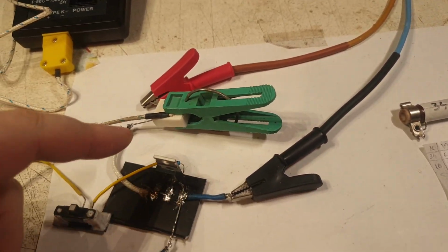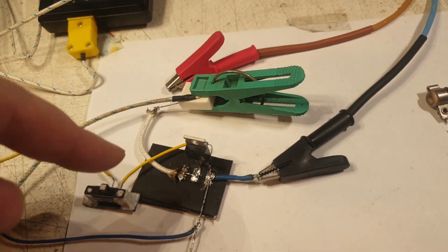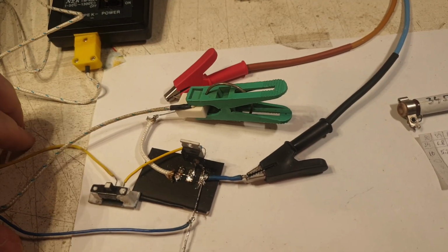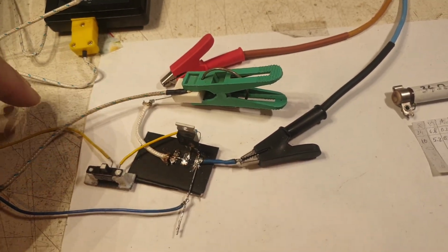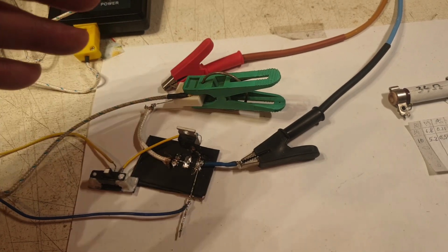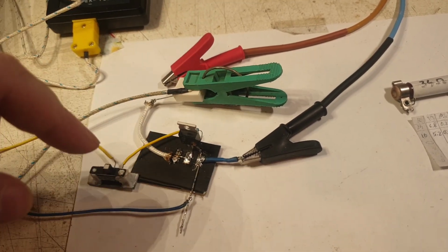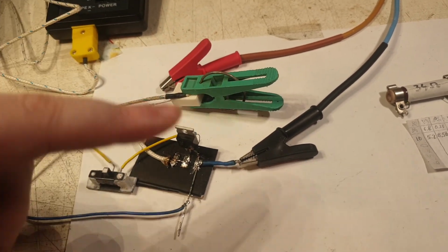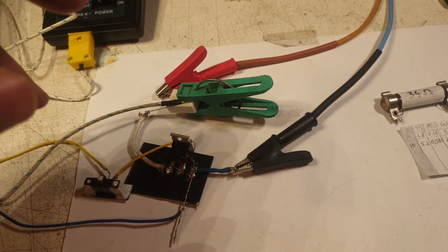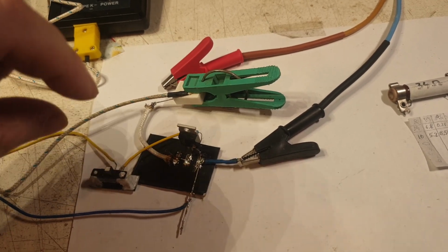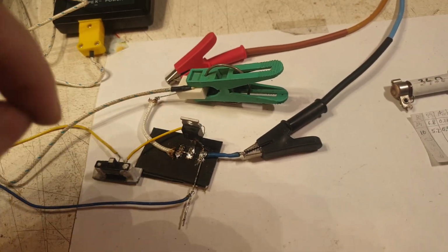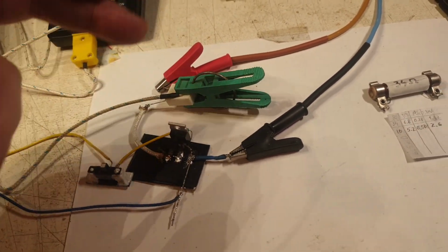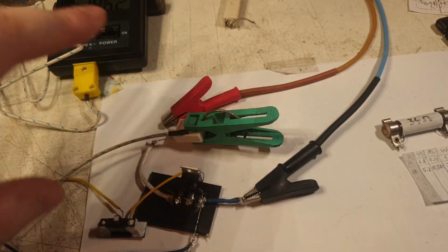So this is the main role of it as a current driver, pretty much driving the current through, and you can switch it and probably even dim it. From my general knowledge, using a PWM, or even a 555 at a certain frequency, will pulse the gate, and probably we will have a 50 percent duty cycle or something like that, at half, and you can dim the amperage flowing through the MOSFET. Probably in those cases the MOSFET will get hot, but in this case, when it's letting all the current through without any dimming, like a normal switch, it's performing excellently.